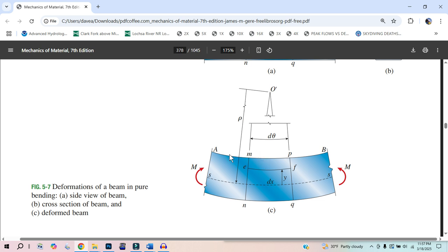There are some interesting problems where, let's say you had an I-beam and then you just welded a thin fin to the top of it out of steel. And then let's say you did it down here. Let's say you welded a thin fin to the bottom of a structural I-beam, and it's pretty tall, just this thin fin of steel, and then something goes on this and really bends it. This thin fin of steel doesn't provide any strength, but what's going to happen is it's going to get ripped to hell apart. It is going to turn into aluminum foil because by geometry it has to move in that shape.